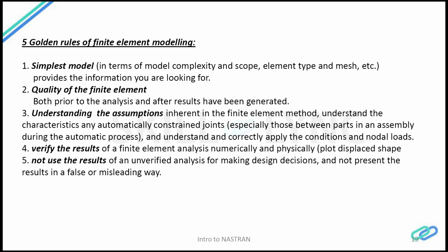Another thing, I would say, is quality. Some of these points have already been covered in the first point. Both prior to the analysis and after the analysis, once the results are generated, you should be able to justify why you have selected the mesh and why you have selected this element.